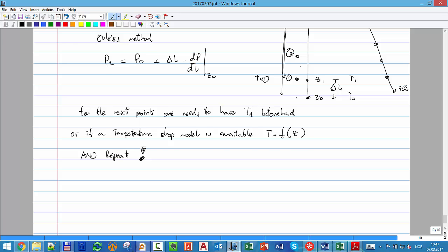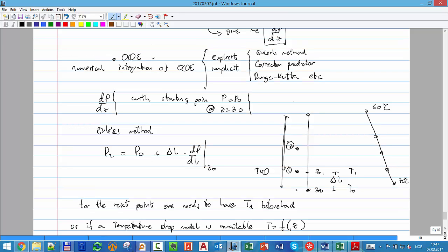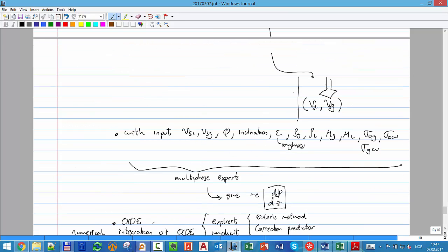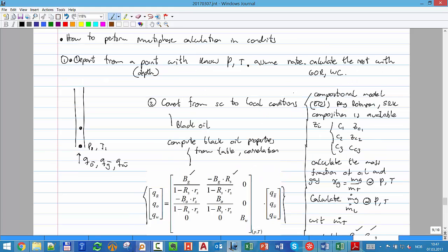I have to discretize, and the most important thing is that after I obtain a solution at the wellhead, I obtain that pressure. For example, if I'm making it equal to the separator pressure, if the pressures are not the same, I have to repeat again. Try with another rate, try with another rate, try with another rate. So it's a bunch of stepwise calculations for each equilibrium point.